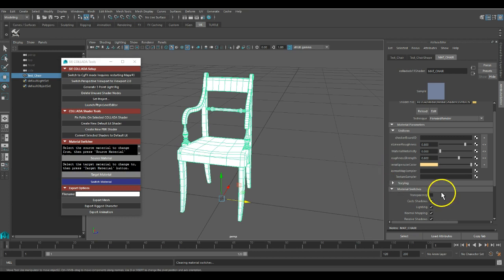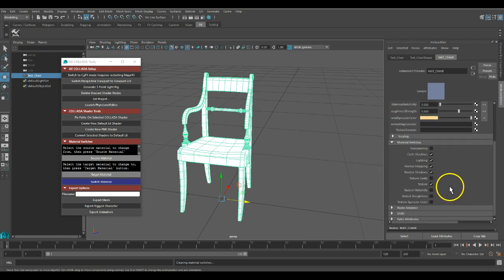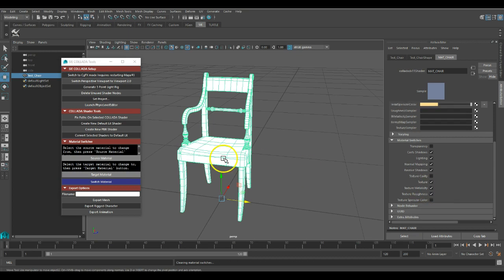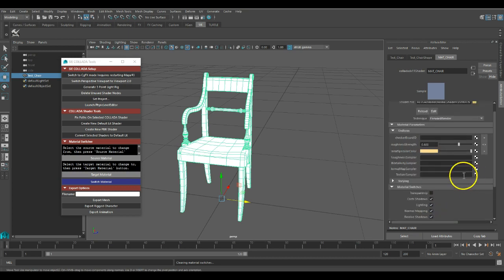and that's because it needs lights and all sorts of stuff. Okay, so with this, we're going to need roughness, because we've got a roughness channel, and we're also going to need the metal channel because we're using the PBR roughness metallic workflow, and this has some metal elements on it, so we're going to need that as well. And by clicking those, we essentially get some extra slots up here to put things in,